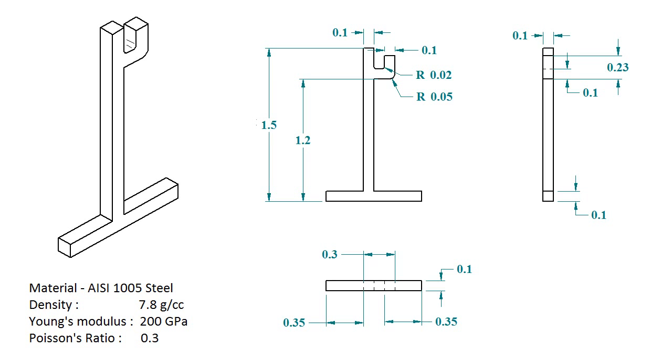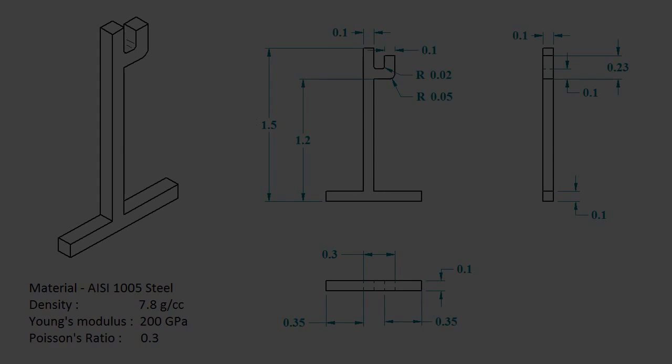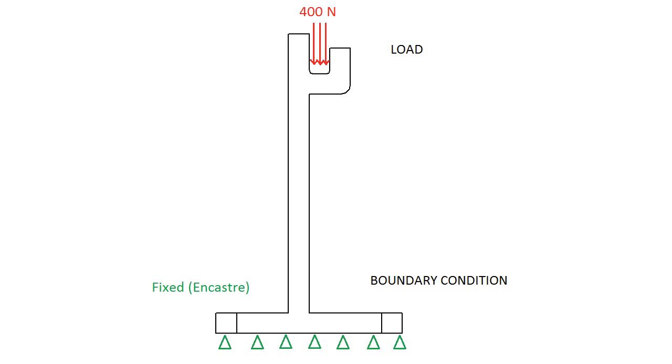When performing finite element simulations, it is not necessary to model every single part of your simulation. Engineers often decide what needs to be part of a simulation and what doesn't, in order to save time and computational resources. We do not need both barbell stands in the analysis. We can just use one and assume it carries half the weight of the barbell. To simplify the simulation further, we don't model the barbell at all, but replace it with a force equal to its weight.